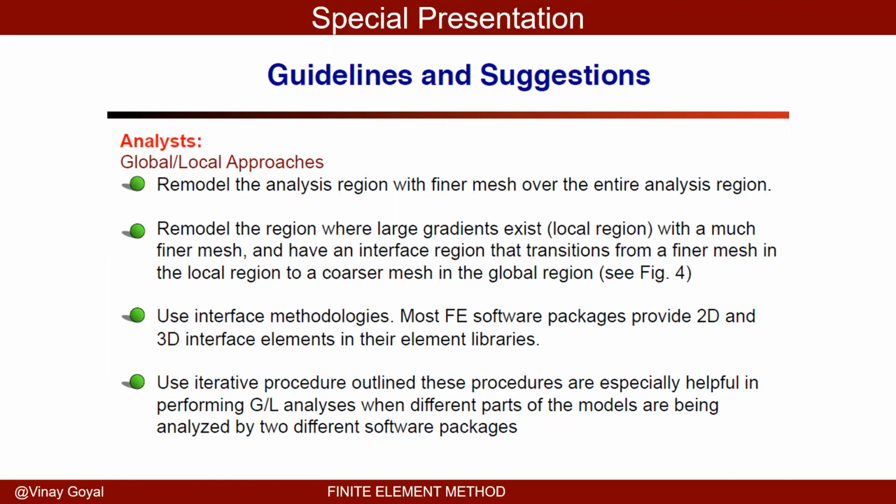In graduate school, they will tell you that if you want to do a free beam, you cannot use K minus omega squared M because K is singular. You have to use M inverse K, because mass is never singular. You can always invert the mass matrix. Find the eigenvalues of M inverse K and take the reciprocals, and you will get the eigenvalues of K inverse M. There will be 0 eigenvalues. So that's what happens when you do not know what the machine is doing or what the theory behind it is. You will say that the software is aborting you.